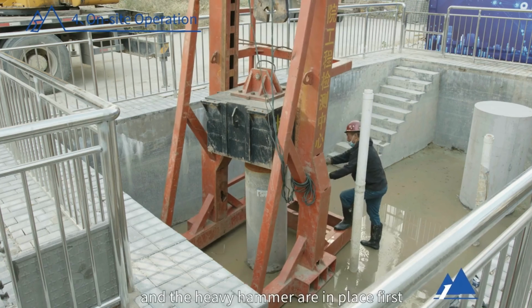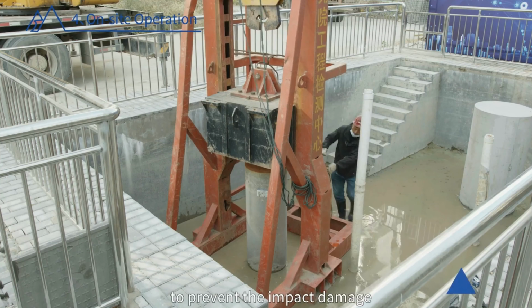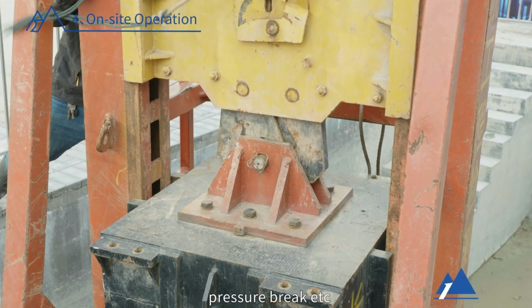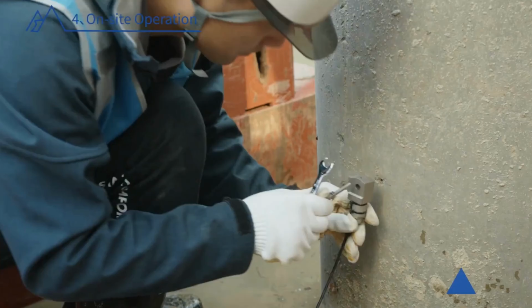The reason why the guide frame and the heavy hammer are put in place first is to prevent impact damage to the installed sensor or damage to the sensor cable, such as pressure break, due to the installation of the guide system.